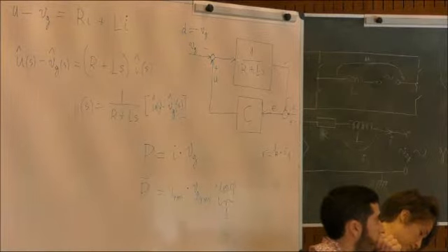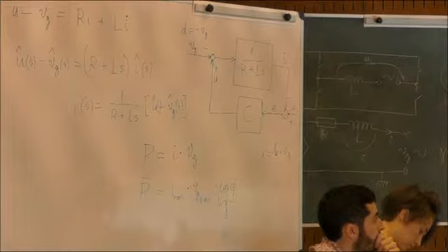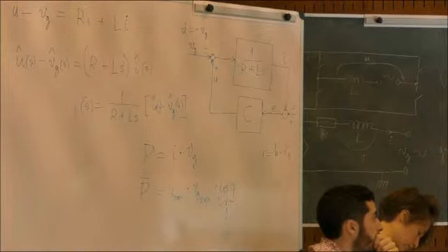A current which is sinusoidal, even if it is out of phase with the voltage, and it's usually out of phase, will not distort the voltage. But a current which is not sinusoidal will distort the voltage, and that's why the utility companies have regulations that consumers are not allowed to be too nonlinear.